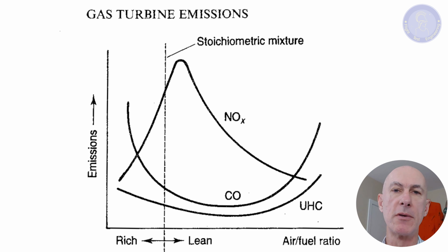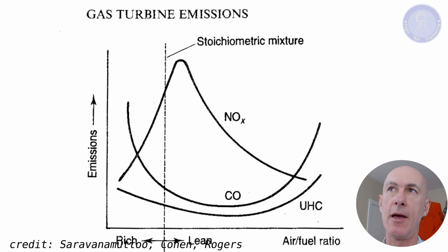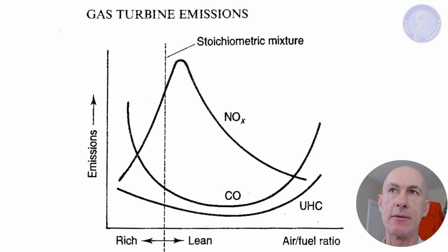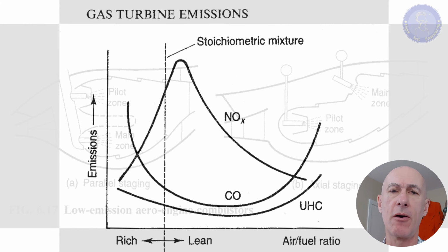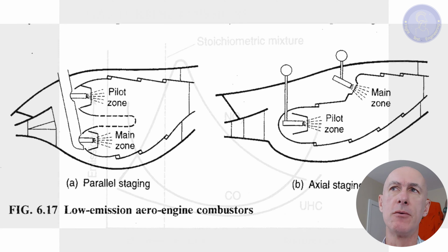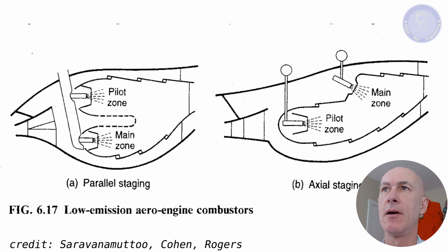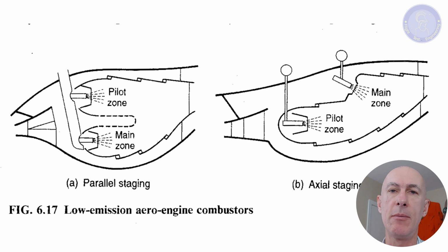We also have problems with emissions. Too hot and we get NOx. So it is an intricate balance. There has been a lot of progress in combustion technology to cope with these restrictions, and the common solution here is to do combustion in stages, where there's one flame that ensures stability, and depending on the power setting of the regime, another flame will guarantee power output.